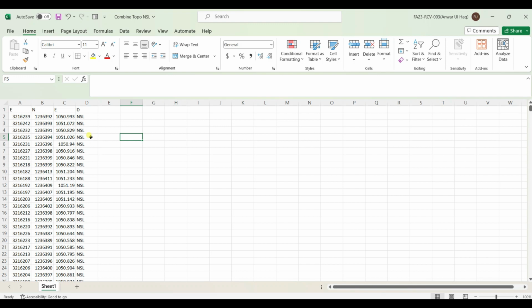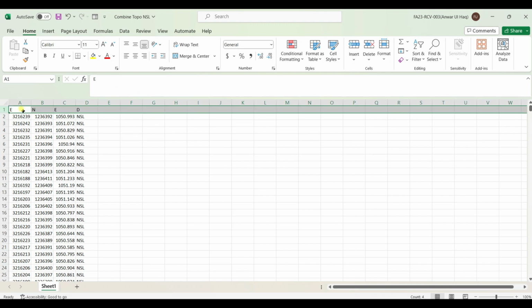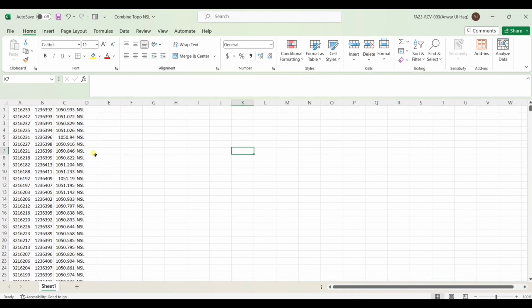When we save our Excel .xlsx file as .csv, then Civil 3D will pick up that data. So first of all, I need to erase all the irregular data. This is irregular because our columns should be coherent, with no external text there. So I need to delete this row.